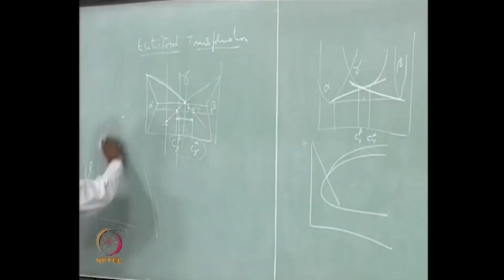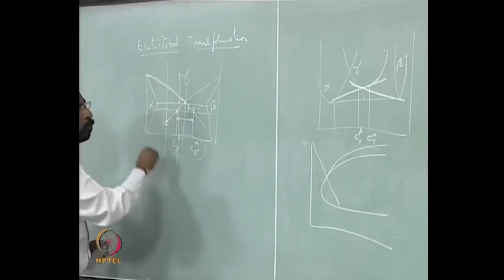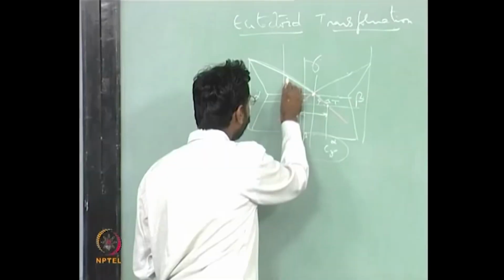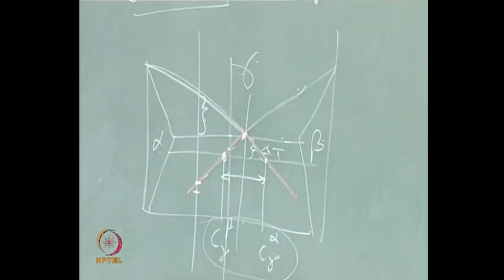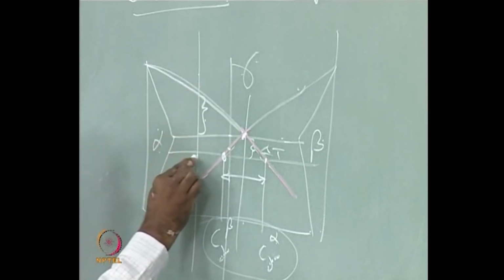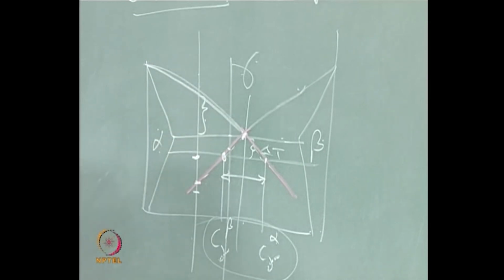Okay. The second issue is, if I take this alloy and I am cooling it, the alpha that is forming here, what would be the morphology of that alpha? People usually see whether the alpha forms there or alpha forms here. For example, if I have undercooled this alloy to this temperature, still you will have an alpha forming because it has not yet intersected this.